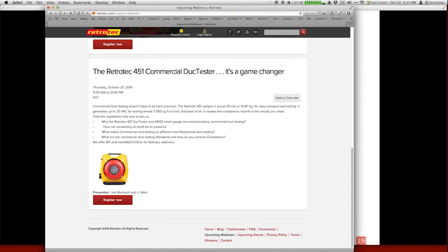or results to be displayed under your settings. And if you go down to CFM, it's either per 100 square feet, or you probably have some metric like meters squared per liters cubed, something like that. So that will actually determine your area and volume. On your settings, you can see that just below CFM, you have a variety of options. Make sure that reads CFM. You have options of CFM, CFM per 100 square feet, or CFM per 1,000 square feet. Any of those will get you back to imperial results of feet and inches.